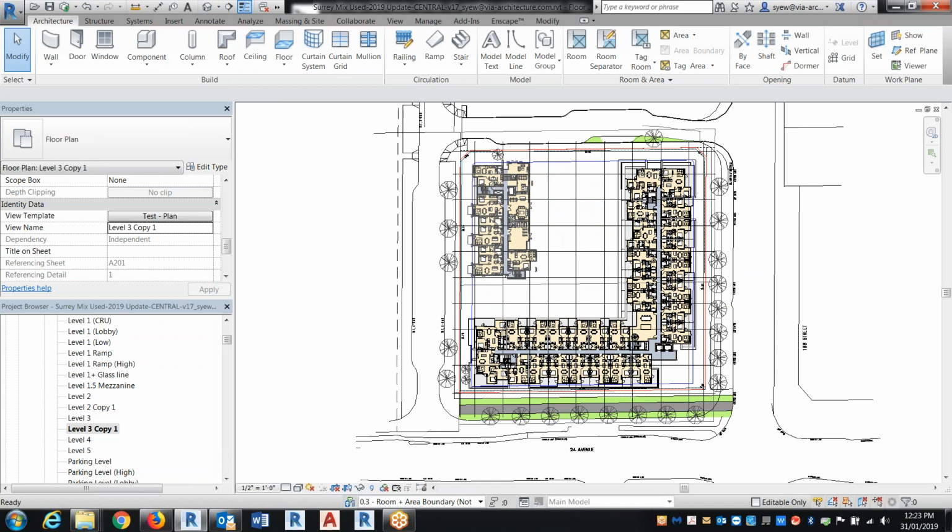I know that when you actually work on an existing project, you will see people start creating multiple scales for different variations. It's a good idea, yes, but at the same time, if you want to have the same settings for your overall plan versus the partial plans, let's say the blown up plans, if they're sharing the same thing, why not just use one template, but change the scale and say do not change the scale. And once you apply that, you only have one template to deal with.